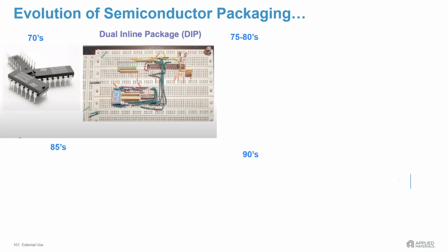And because of the nature of the package, how much can you really expand on it? Because as you want to take more and more logic into that device, into that die, you want to have more and more interconnects out to the real world. And therefore, how many legs can you deliver on this sort of package?